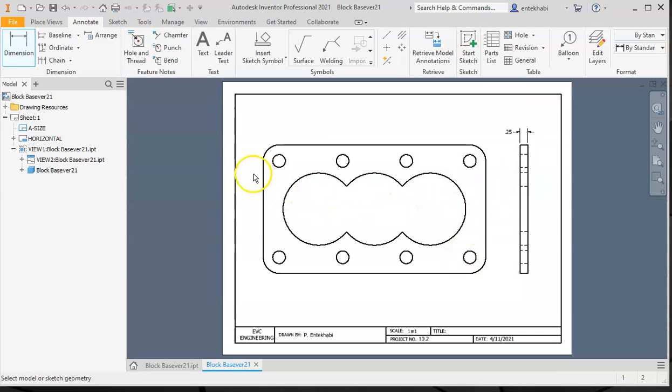Okay, let's do some other changes. As required in most of the drawings we are doing, we are going to change the color for dimensions. We are going to change some of the center line settings as required. Let's begin adding some center marks first. I'm adding the center marks for all the holes. So notice all the holes are the same size and same spacing, and all we need to do is basically add one dimension and describe that there are 8 of them.